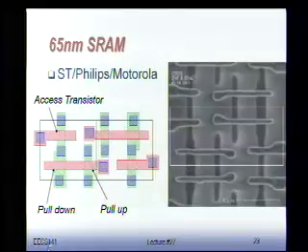But anyhow, this is what it looked like in real life. This is a memory cell. This is a 65 nanometer SRAM cell from Motorola, Philips, and ST, part of the Crolles Alliance type of design. You can see it's pretty tricky. It's very dense, and you can see with all the lithography effects, some of those wires that you think are nice thick wires and contacts really get very skinny. They really push very carefully on design rules and still get meaningful transistors, because those things are getting very small, very skinny. And you still have to make sure it works correctly.